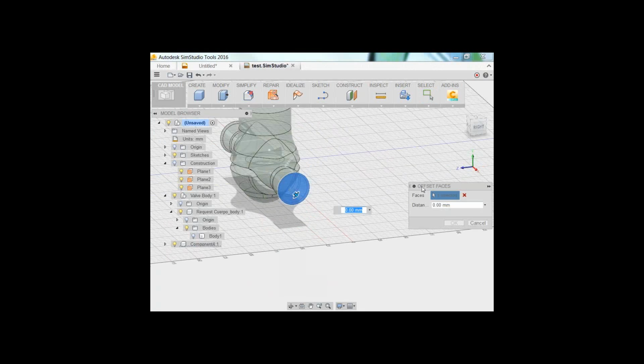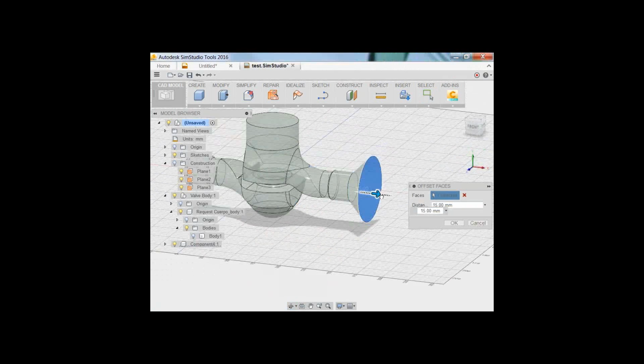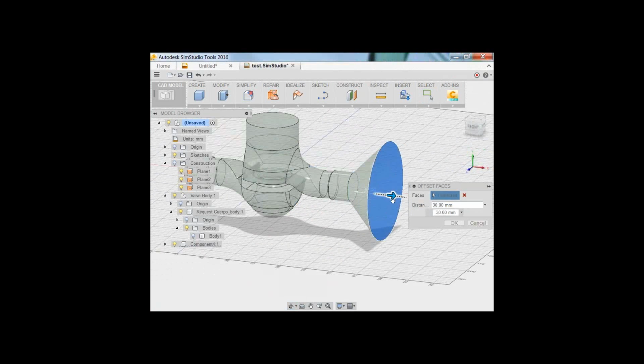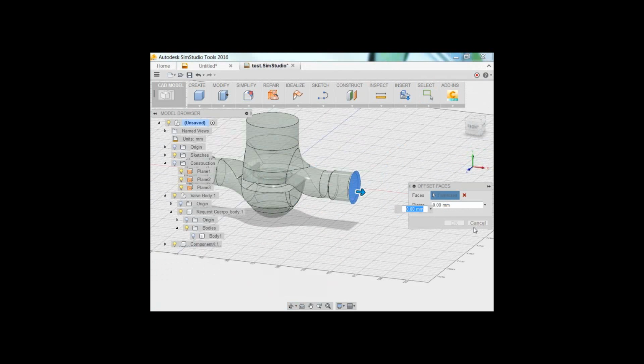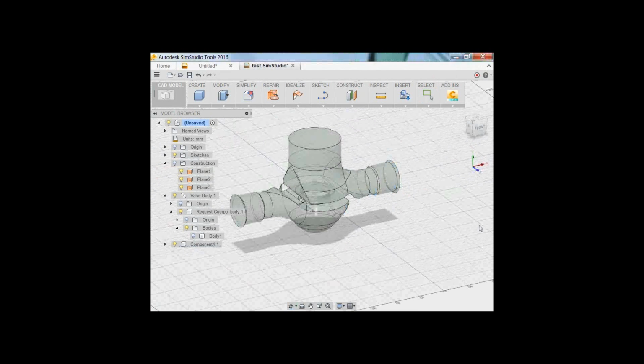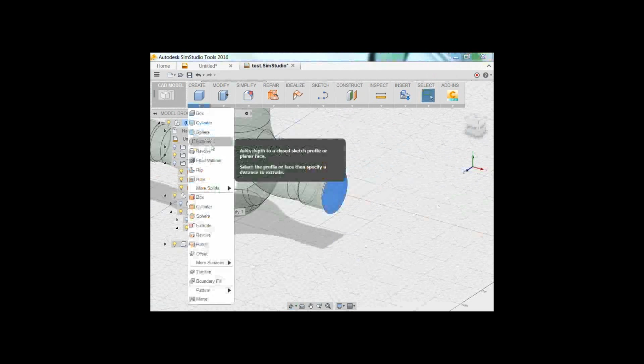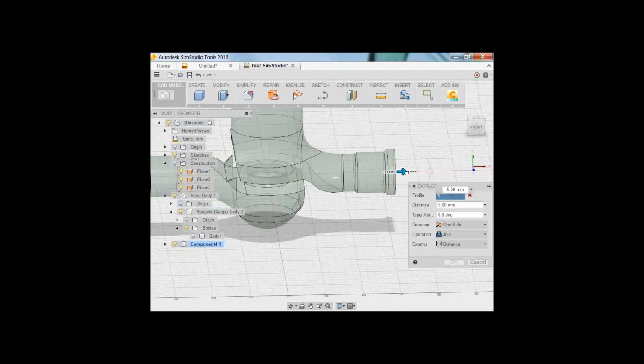And again, I believe this is going to work, but we'll try. Oh, this is a little directional one, so this one's going to be a little tricky. But again, I can show you how to do that using some different tips and tricks. You should be able to do it. Maybe extrude? Yeah, let's try extrude. The reason that you want to do this is because if there's any recirculation around a face, that can cause us divergence.